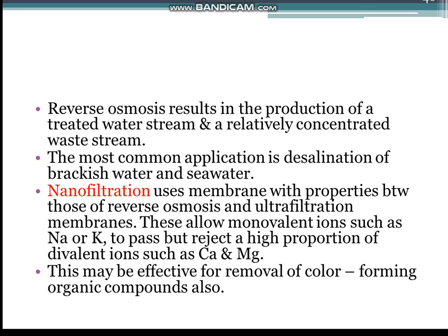Reverse osmosis results in the production of a treated water stream and a relatively concentrated waste stream. Typically, operating pressures are in the range 15 to 50 bar depending on the application. Reverse osmosis rejects monovalent ions and organics of molecular weight greater than about 50 daltons. The most common application of reverse osmosis is desalination of brackish water and seawater.